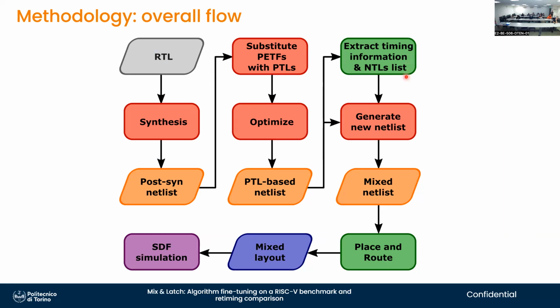We do our magic that is going to be described in the next few slides, and then we add negative latches. This will fix most hold time violations. There will still be a small number, which are small in magnitude, and those will be dealt with by the final place and route, which is able to fix those because they involve very little effort.